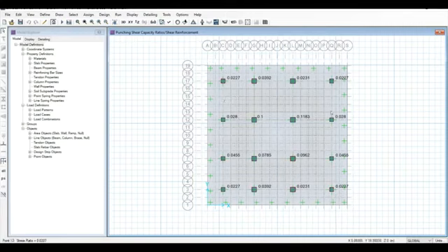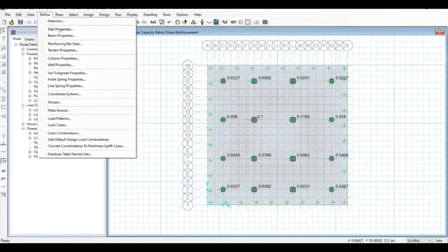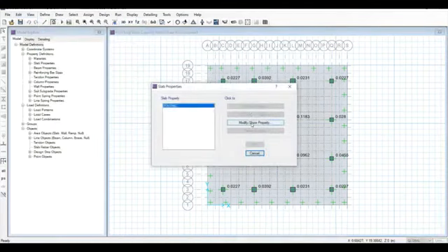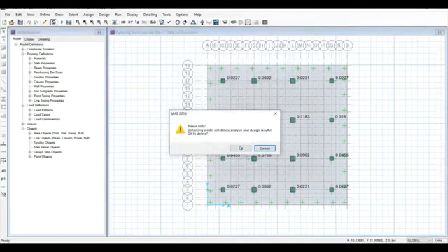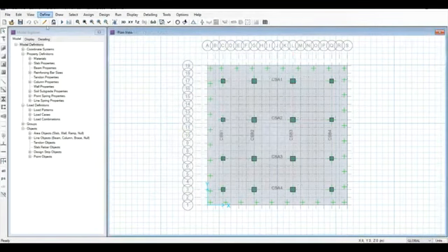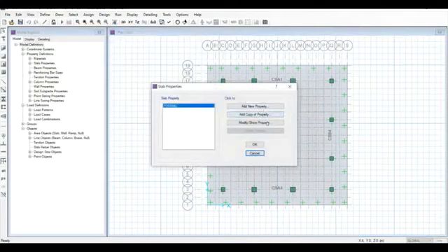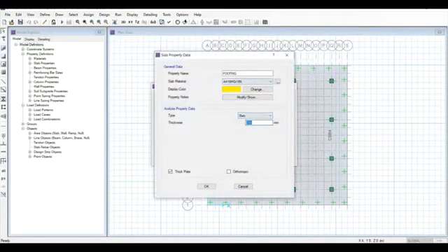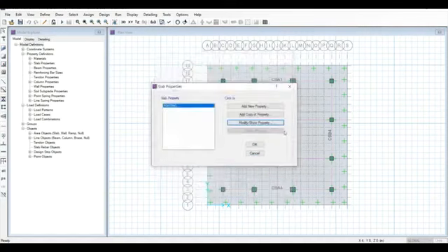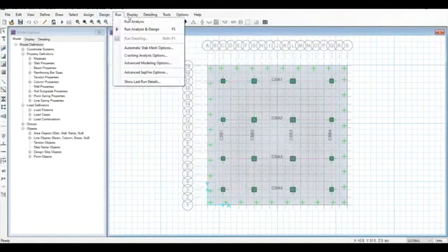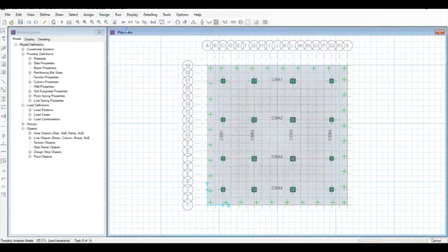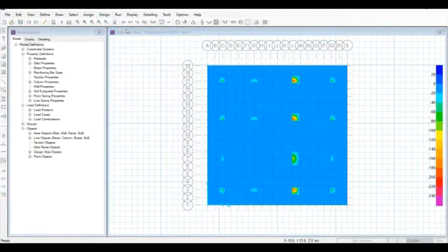If we have any different values here, then we need to go for define and change the slab properties of footing. Modify. As we are in locked position, we need to unlock it first. Define slab properties, footing, modify our slab footing, and change the values here from 200 to 500, and then click OK. Then you can go for an analysis again. As we have already got safe values, no need to do this.